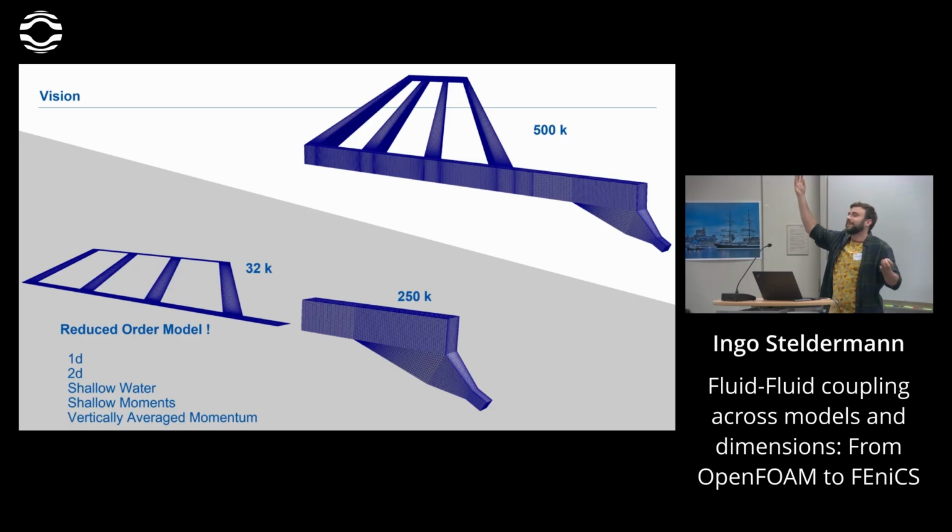And shallow water equations is like, reduce it as much as you can, right? Then you end up with shallow water. It is essentially hydrostatic, so the pressure is as easy as it can be in terms of solving it. You can have explicit schemes. You don't need to solve the Poisson equation, whatever. So it's very cheap and easy, and it's trivial to do it on a GPU even, right?